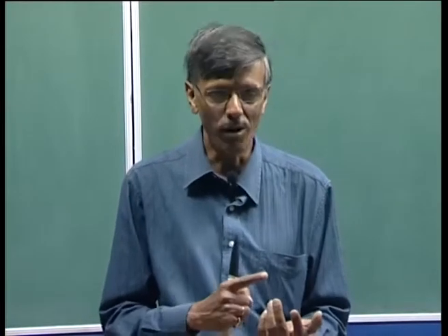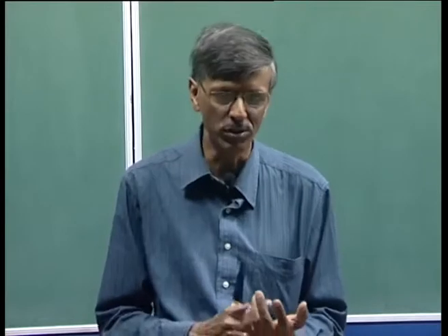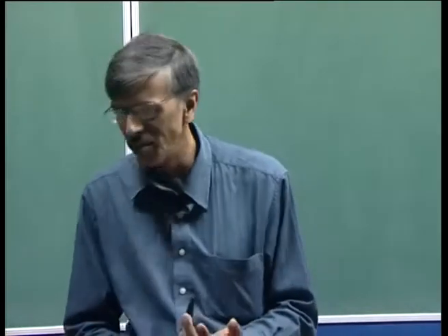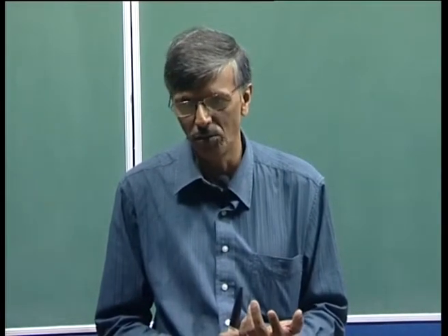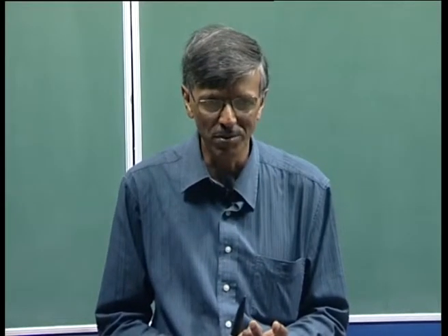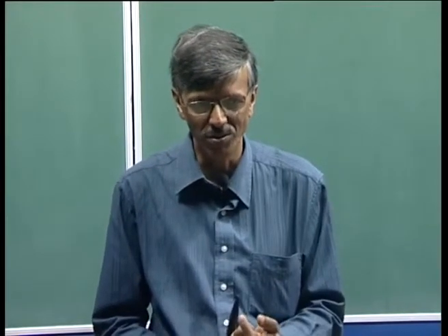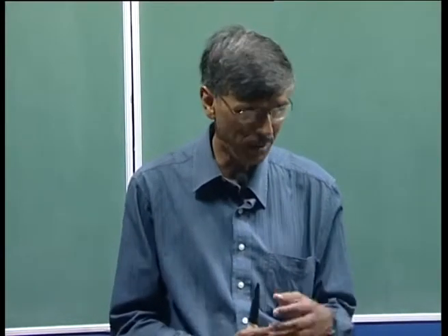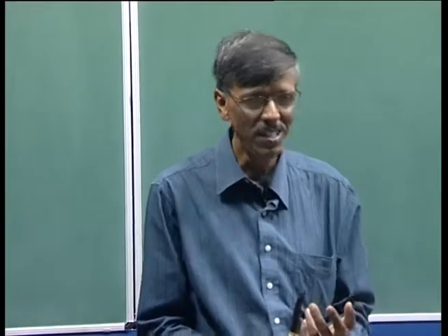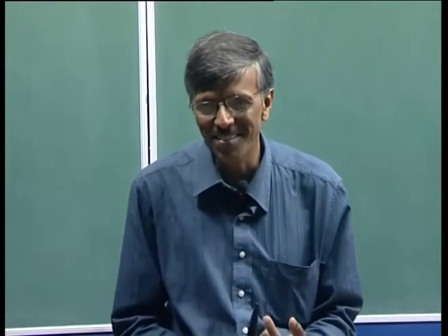Now, we have also answered the question of, do we have upstream propagating modes? Yes, we do. We have just now talked about what happens if the boundary layer is excited at a very, very low frequency. Your disturbance field is very special. It is not 2-dimensional, right? You get only 3-dimensional solutions. 2-dimensional eigen modes disappear. However, despite the response field being 3-dimensional, it also has a very interesting attribute. It looks like 2-dimensional because Vgz is 0.